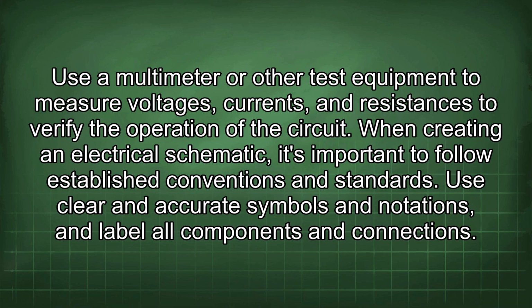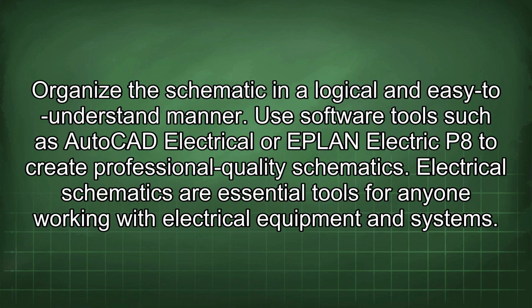When creating an electrical schematic, it's important to follow established conventions and standards. Use clear and accurate symbols and notations, and label all components and connections. Organize the schematic in a logical and easy-to-understand manner. Use software tools such as AutoCAD Electrical or Eplan Electric P8 to create professional quality schematics.